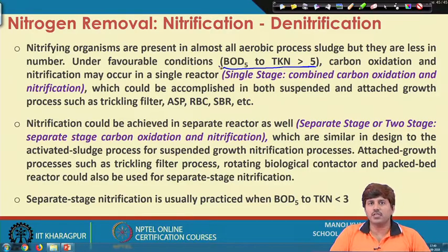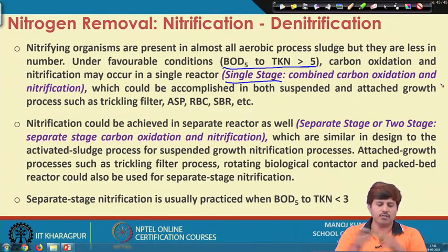That is called single stage or combined carbon oxidation and nitrification, or combined CBOD and NBOD removal, because we are removing carbonaceous BOD and nitrogenous oxygen demand together. Since this is done in a single stage, we call this a single stage process, which can be accomplished in both suspended as well as attached growth systems, like activated sludge process, rotating biological contactor, sequencing batch reactor, all those things.